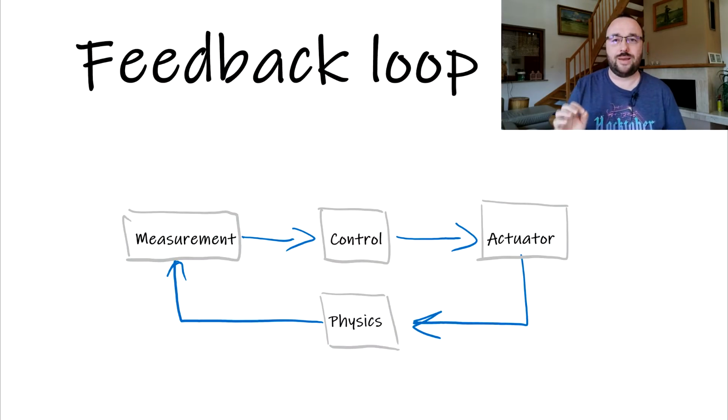If we are talking about the control theory and the PID controller, the name we will explain slightly later, you have to understand that the PID controller works only if there is a feedback loop somewhere there, where the physics is applied. That means we have the measurement phase when we measure the current state of something, like for example in case of the multirotors, we measure the angular velocity by the gyroscope.